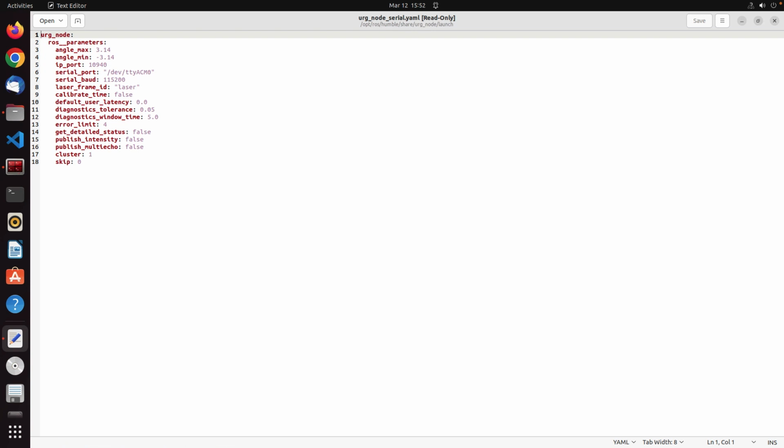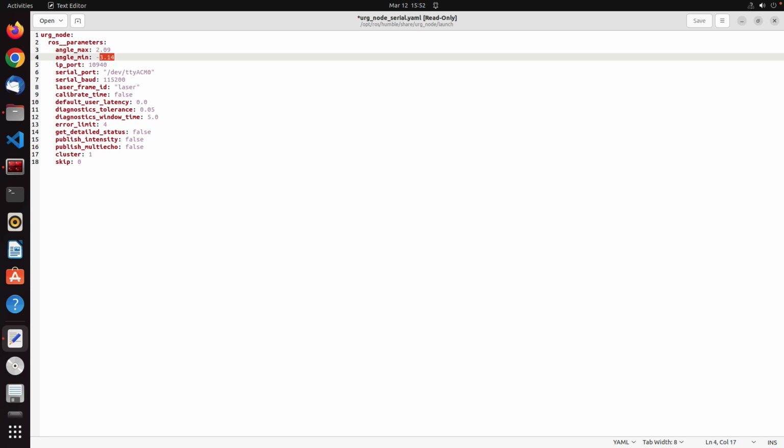It specifies the maximum angle out of 360 degrees, minus 80 to 80. I think this is probably not correct for this configuration, so I can change it. It's minus 20 to plus 20, so let me change it to 120 degrees. What is the equivalent in radians? Divided by 180, multiplied by 3.14. It's 2.09. So 2.09 here, and 2.09 here.